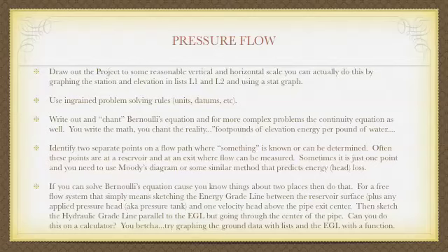That one assumes no friction. This one does assume that you're losing energy to friction on a constant basis through the entire run of the pipe. You then realize that you're going to step down and lose a chunk of energy any time the flow path makes a weird turn, like through a fitting or in an entrance.